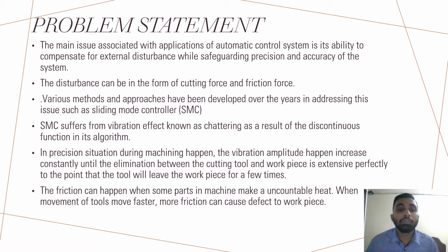Sliding mode controller suffers from a vibration effect known as chattering as a result of the discontinuous function in its algorithm. During machining, the vibration amplitude can increase constantly until the tool will leave the workpiece a few times.